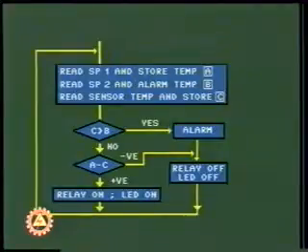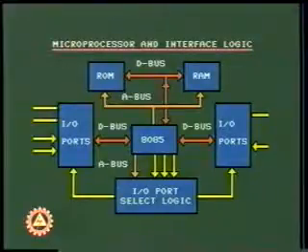If the process temperature is less than the set value, then the relay is switched on. If the need arises, it will sound the alarms and may also change the LED status. The system also displays the temperature of the process. For this, we need a port line and multiplexing mechanism in order to conserve the total power consumed. Since all the inputs and outputs are I/O mapped, we need to have programmable peripheral interfaces and I/O decoding logic.